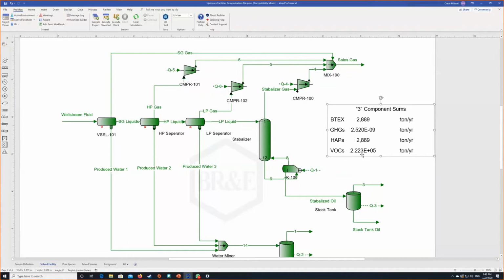So this is generally unacceptable for a lot of countries' environmental standards. So what I can do is, instead of putting in a boil-up ratio, I can design or operate my stabilizer to target a particular RVP spec, a very common RVP spec. I'm using English units because I'm based in the United States and that's what we use here, but a very common RVP spec, and I think you guys might use this as well, is about 12 PSI.